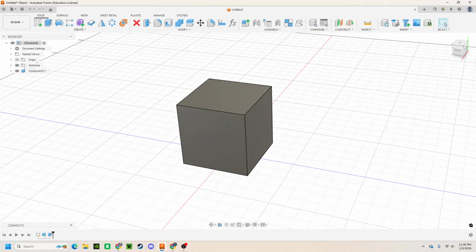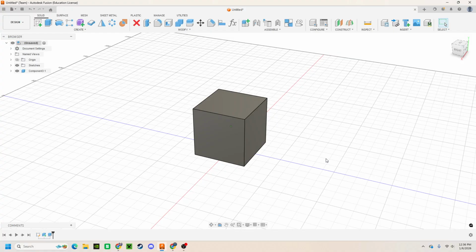Before this, bodies were completely dependent on their initial sketch. This means that their location only ever depended on where their sketch profile was. Now, we can have components move around, because their position is technically unconstrained, in a way. Since their position is now undefined, in order to work with them and build off of them, we need to define their position. This is really easy to do, and it is called position.